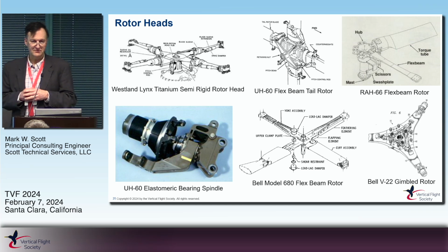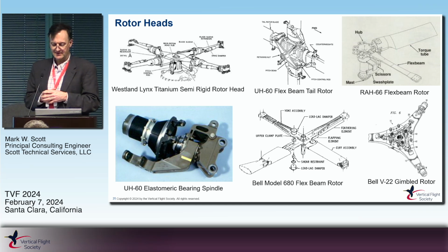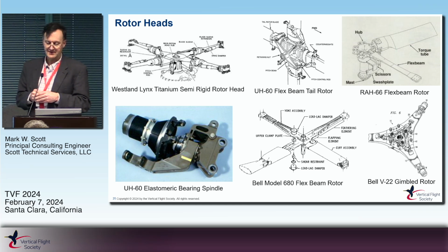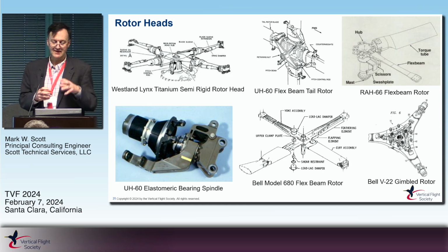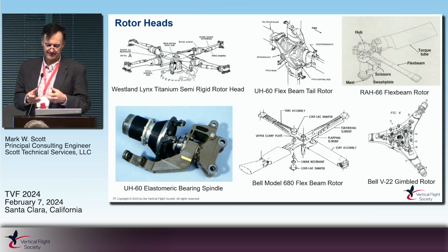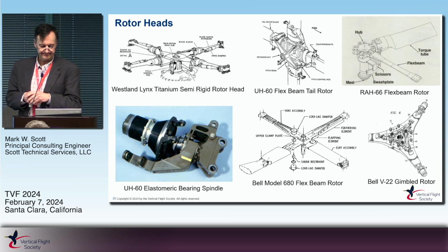And then tilt rotors too, different animal, right? You don't want something super stiff. In particular, you don't want any of this kinematic feedback where the rotor flaps and you put in little accelerations or decelerations in the rotational rate of the rotor system. So I came up with things called the drag link rotor. And just really fundamental to making a tilt rotor work and getting up those flutter speeds up to the speeds you need to match the performance you want in the aircraft.